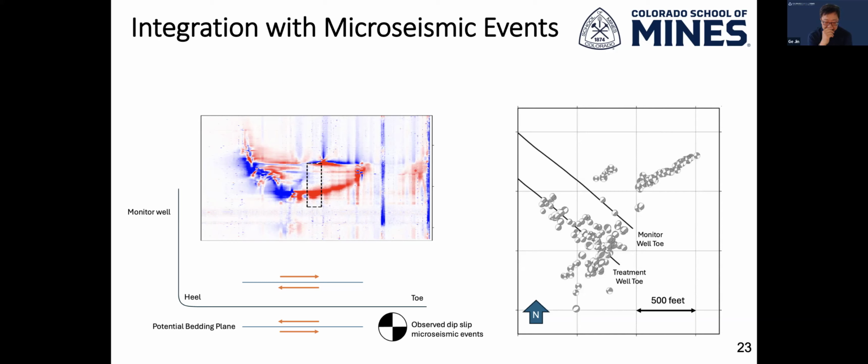Yeah, so I see why you're asking about the dip. I argue with people a lot about this. Personally, I don't believe the principal stress has to be 100% vertical. There's a chance that the principal stress can be slightly tilted from the vertical, and also the bedding may not be 100% vertical. Given that there's a shear motion in there, I'm 100% sure that the bedding plane is not perfectly perpendicular to the principal stress direction. Otherwise, there shouldn't be shear.